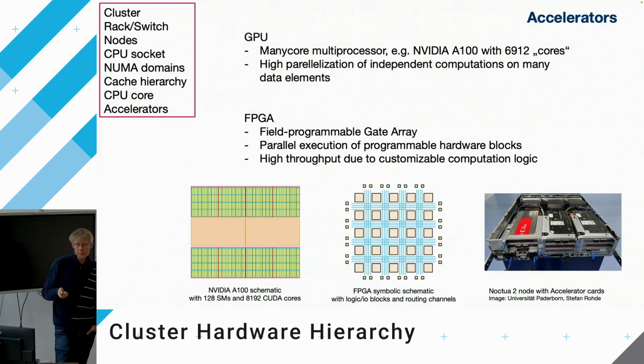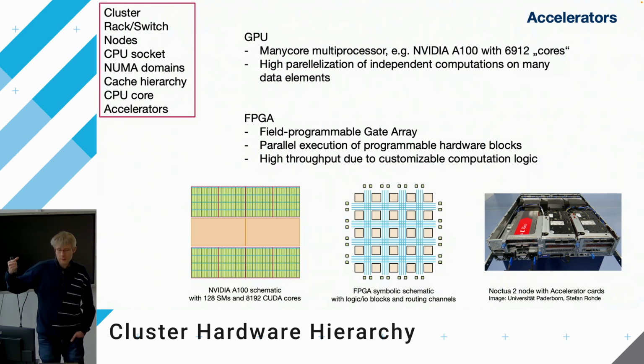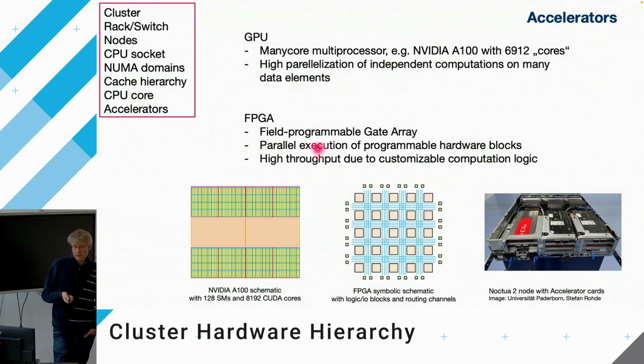And we also have FPGAs. So these are a specialty of our compute center here, where we use and research these types of accelerators. These are field programmable gate arrays. And this basically means that on these chips, you have a grid of these computing resources, and you program all of these small compute blocks, and then you connect them and decide how the data flows through these compute blocks.